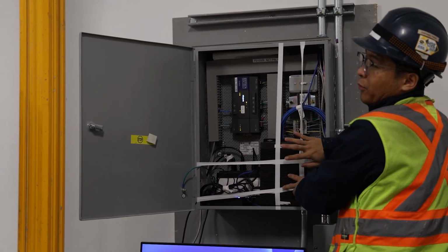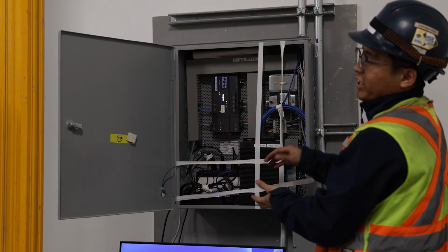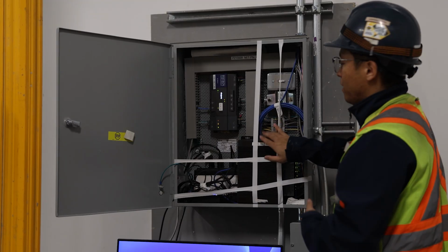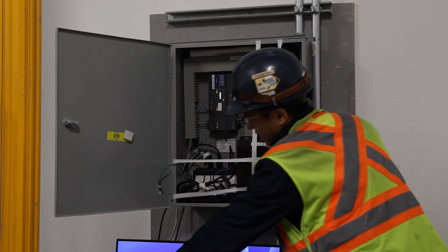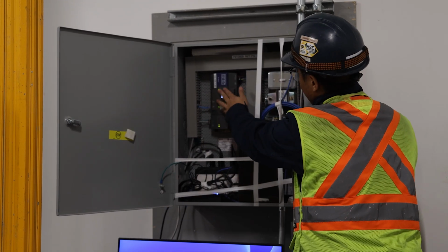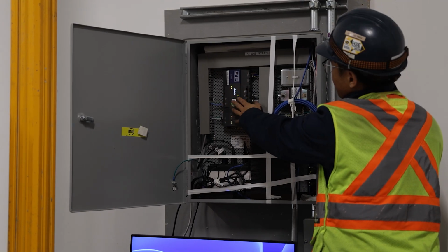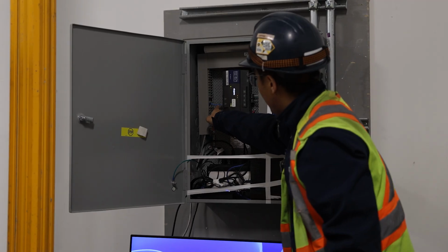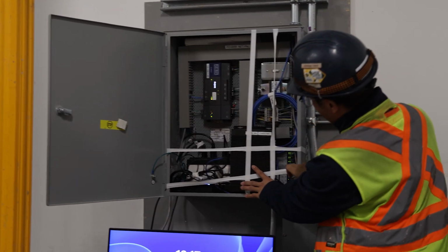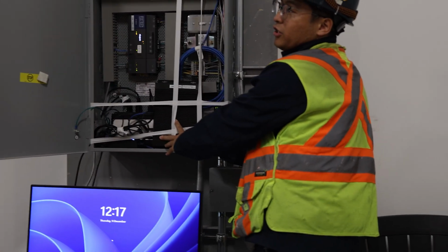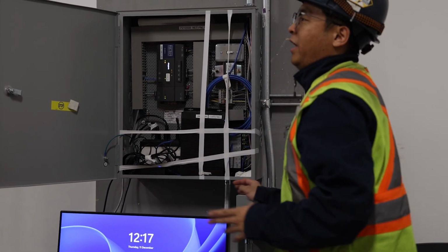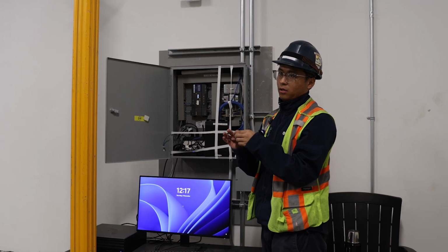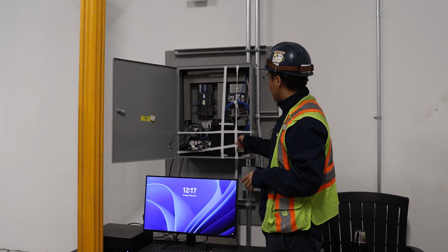Right now, we have a temporary server. This is our computer. We just leave it here so we can do some work. Later on, this will be removed. This is the Jace that does all the communication for the controller, and it hosts the graphic. The communication is through this port, and behind this computer, we have a network switch. All the IP devices, including the penthouse DDC controller, water-to-water heat pump, and air source heat pump, communicate